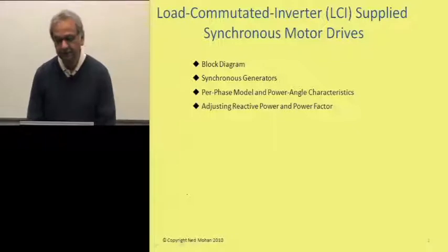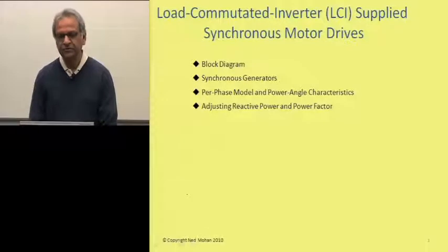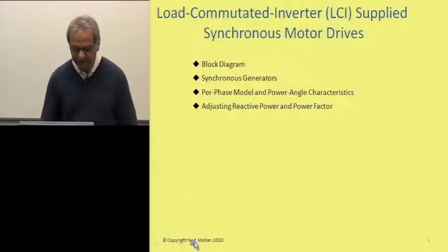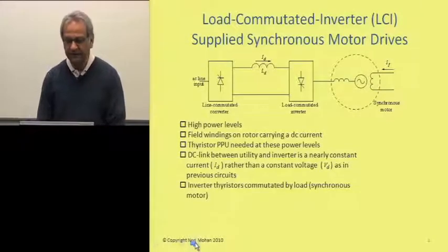In this module, we will look at synchronous machines in very large sizes, and some of them are controlled by thyristor-based converters, as we'll see. They are called load-commutated inverter supplied synchronous motor drives. And we'll also look at synchronous generators, which are used, for example, in power plants. So let's start with this LCI drives.